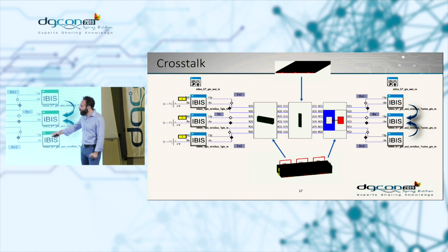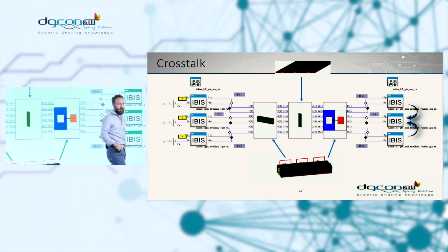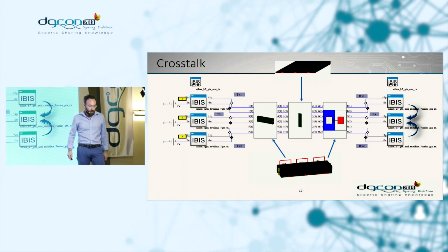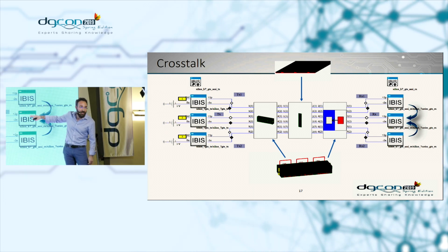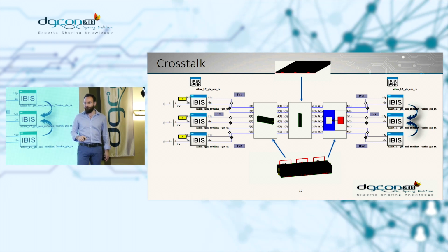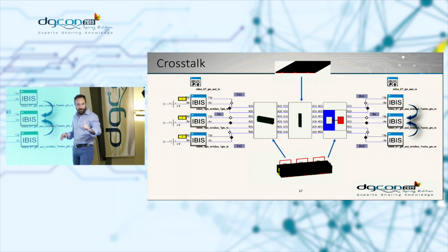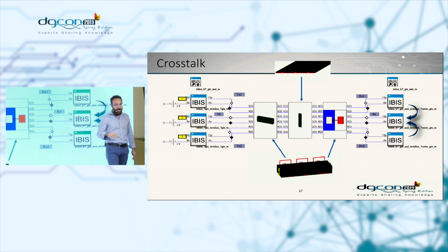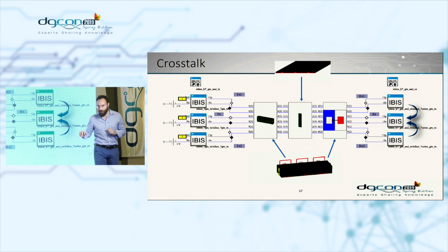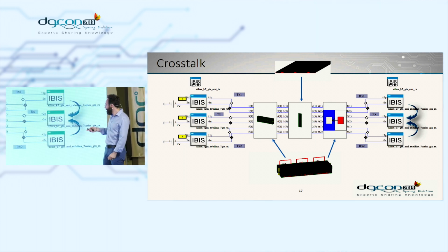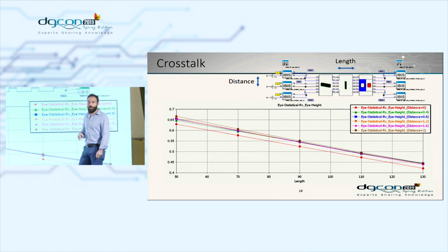But let's introduce something more. Let's also introduce the net made by using a 3D software simulation, a 3D tool directly, and have a look at more than one net close to each other. This generates problems because at the moment we have analyzed only one transition, only one net, alone, without anything else. Now we have more than one net. And this generates noise. This generates crosstalk. This generates problems that we need to take care of, especially in a very complex board.